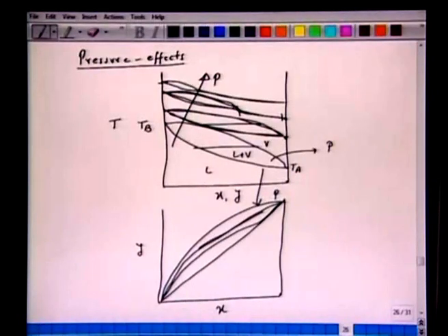It has hit the 45-degree line like this and like this. So this is increasing pressure. Again, from the Txy diagram we have plotted, this Yx diagram, one can take the projections of Y and X, take X here, take Y here, go to the 45-degree line and connect with this X, etc. So one can do this.